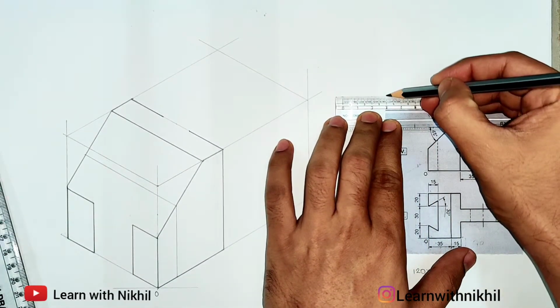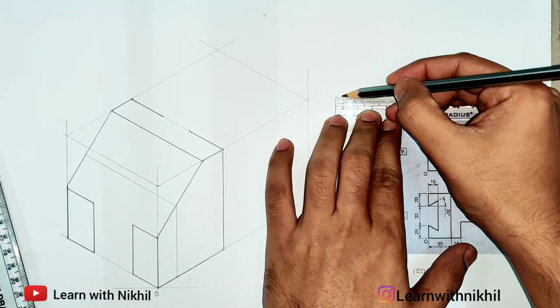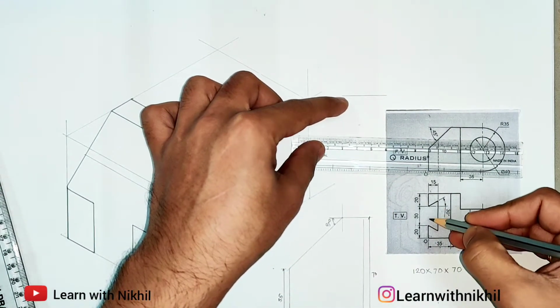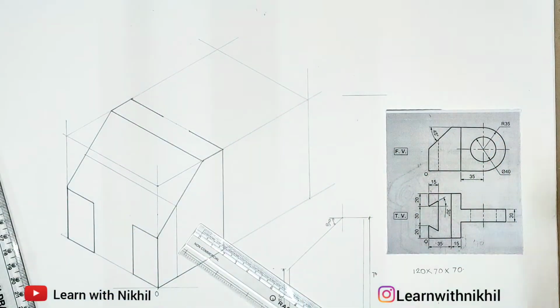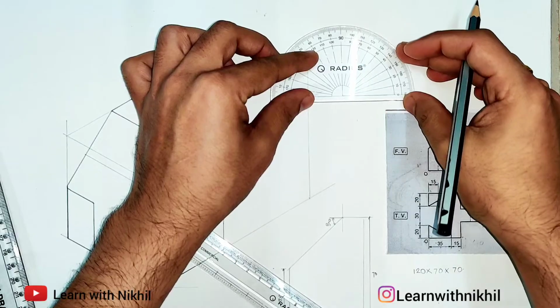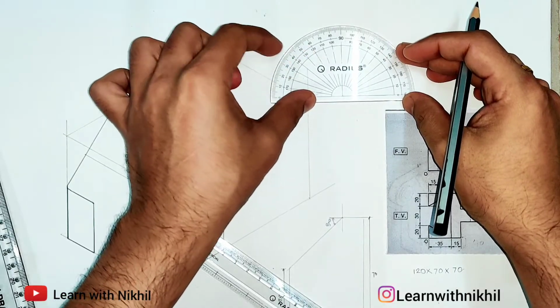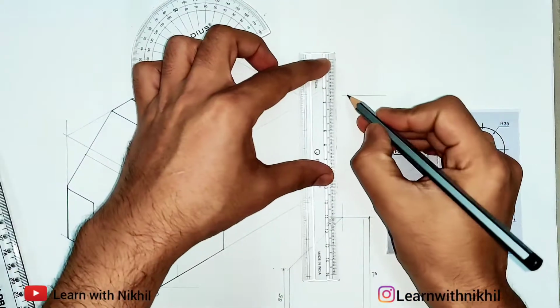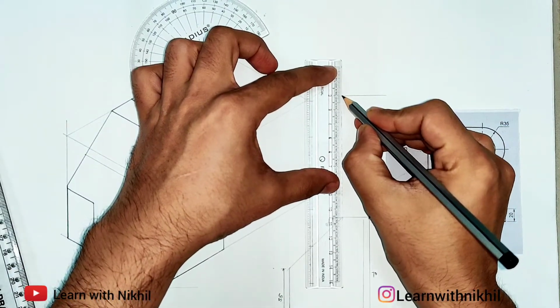So first this is the 30 millimeter distance. So this is this gap. I'm drawing, this is 30 millimeter. Then we have to draw the angle, that is 30 degrees. So this is the 90 degree part, and from 90 degrees left side 30 degrees.